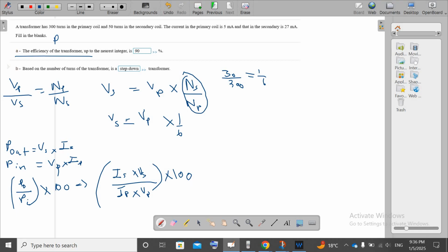But I know that VS is VP over 6. So therefore, IS times VP over 6, over IP times VP, times 100.